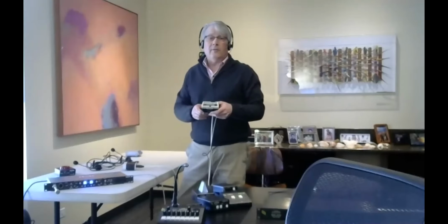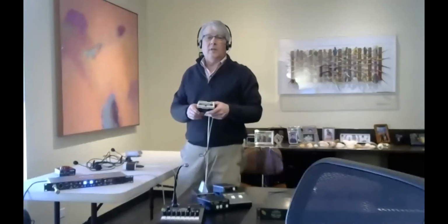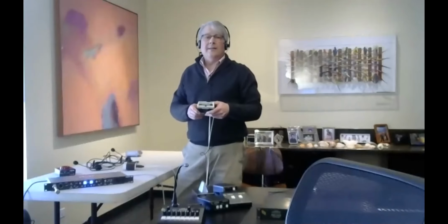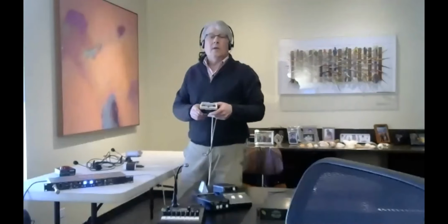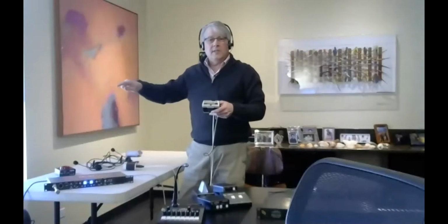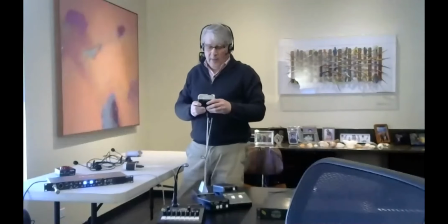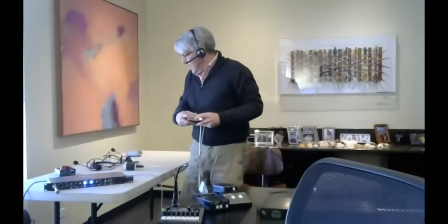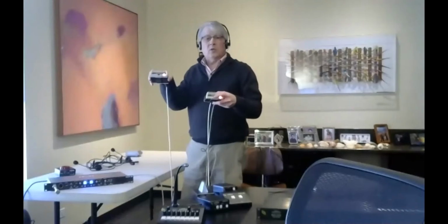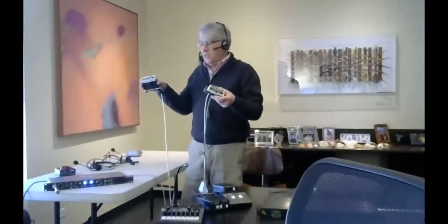And what Clearcom did, it's fairly clever. What happened in the 1970s, they put a DC voltage on the audio pin, and that's how call works. They ramp up and down the DC so you don't hear a click, and that's how when you press call, you see the light up there, and you'll see it light up because over the audio path, you have DC.